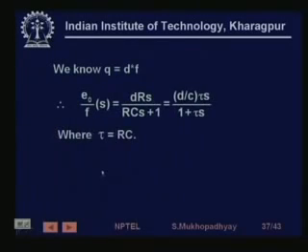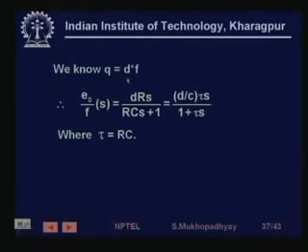that if you are talking of a force, and we say that the charge generated is proportional to the force applied on the crystal, then dynamically the EMF generated by the force is like acceleration. If some mass is accelerating, then the force applied on the crystal will be proportional to the acceleration.